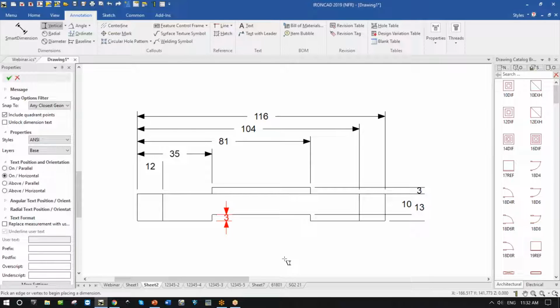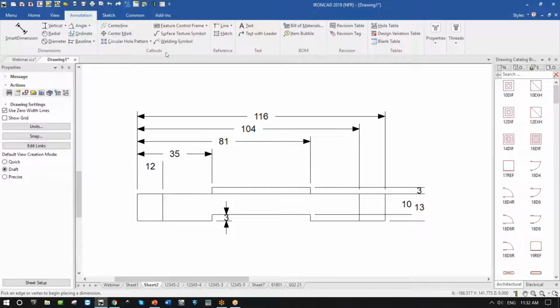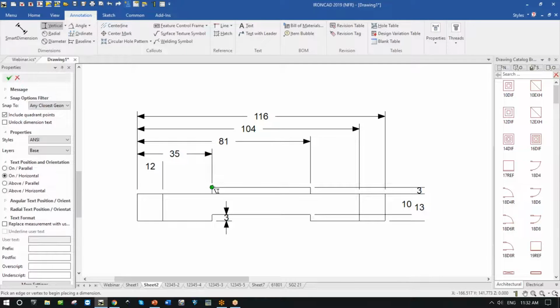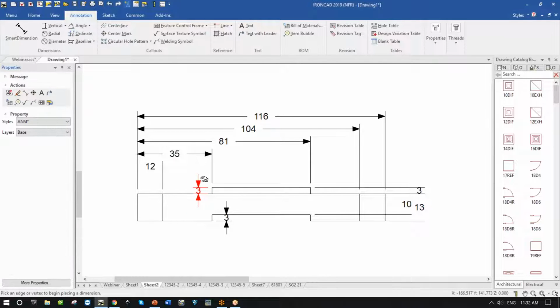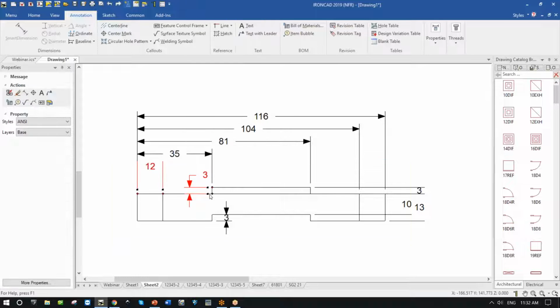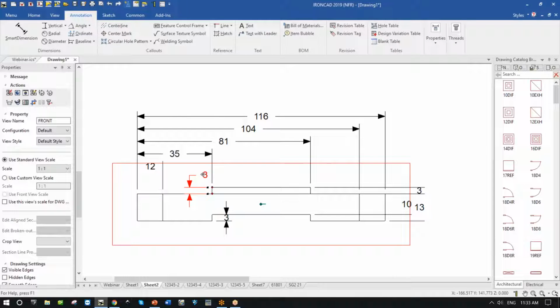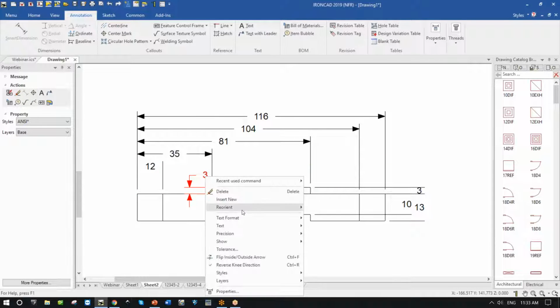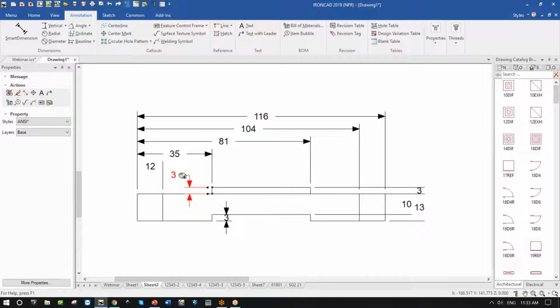Oh, yep, that's exactly what we wanted. What about on the top? Yes, that was also supposed to be 3 mil on there. So go ahead, give me a vertical dimension from this. And I might not like the way those are, so of course I can just later pick them up and move this. And oh, wait a second, that dog leg is going the wrong way. So the idea is that it's very easy to pick on a dimension and just say, you go the other way and move that over. So you have control of how these things work.